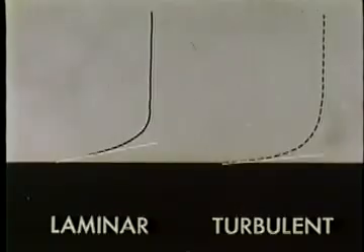There are larger shear stresses and more momentum in the turbulent boundary layer than in the laminar layer, and the turbulent boundary layer is slightly thicker. In the diffuser, the turbulent boundary layer along the bottom wall does not separate, while the laminar one does, because the three-dimensional interchange between regions of high and low momentum fluid in the turbulent layer is more effective than the molecular diffusion in the laminar layer.